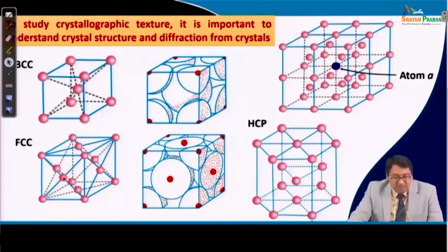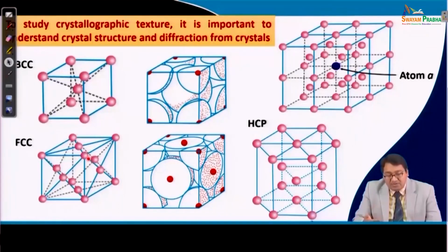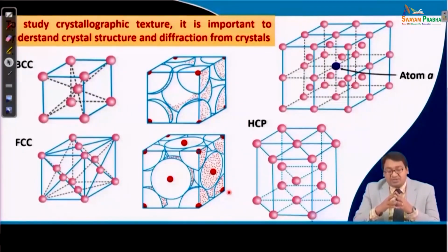You see, there are 1, 2, 3, 4, 5 and 6 faces in the cubic unit cell, which makes that 3 atoms per unit cell in the faces, plus 1 atom from the corners of the unit cell, which in real life looks something like this. And therefore, there are 4 atoms in a face centered cubic unit cell, making it a very closest packed structure.